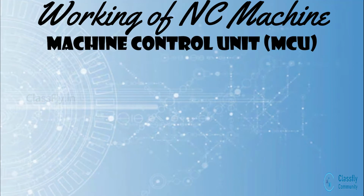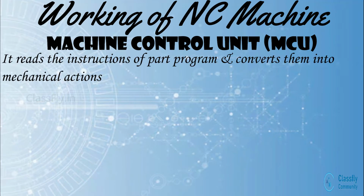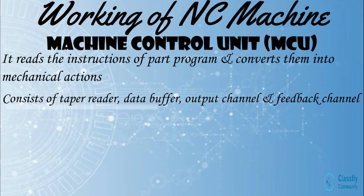Next, the machine control unit, commonly known as MCU. Well, this is the heart of the NC machine. This unit consists of electronics and hardware that can read and interpret the program of instructions and will convert it into mechanical actions which has to be performed by the machine tool. Well, the machine control unit is responsible for deciding the cutting speed, the feed, the depth of cut and other parameters for a tool operation. It comprises of a tape reader, a data buffer, signal output channels and a feedback channel.